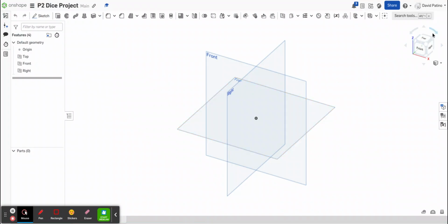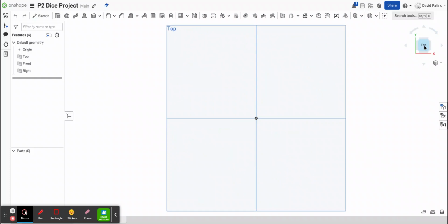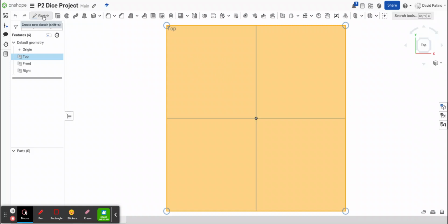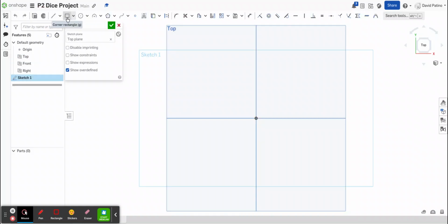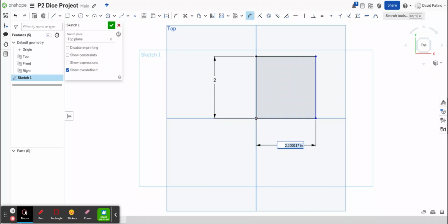All right, so I always start at the top using the nav cube: click top, and then we start our pre-select of the top construction plane. And I'm going to click sketch. So now we're ready to create a rectangle. Hover over the origin, click, drag, click. Move to the dimension tool, hover over, it glows orange, click, drag, click. To enter, hover over the horizontal line, click, drag, click. To enter, we're ready to go.